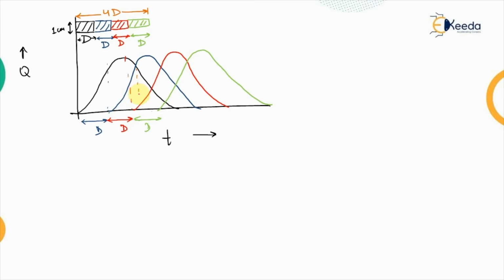Now corresponding to this value that I have denoted with this brown color, we have two ordinates, one for the black and one for the blue. So we will add up all these values and we will get the resulting hydrograph, which will be like this, ending at this point.